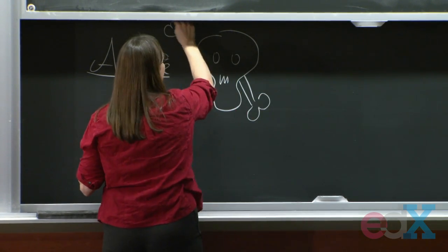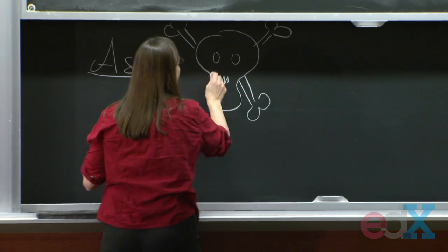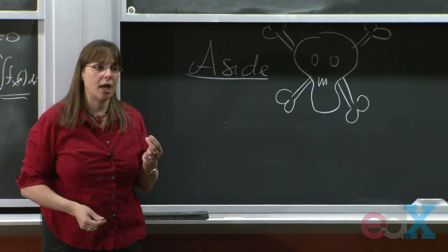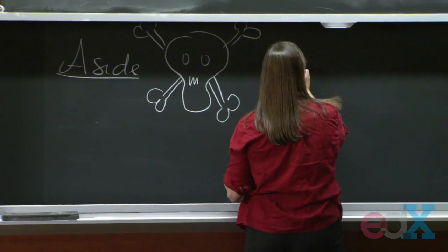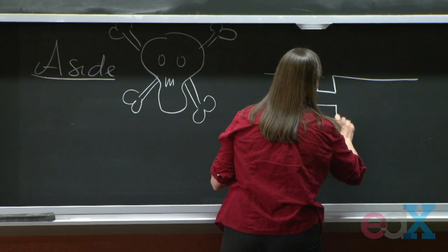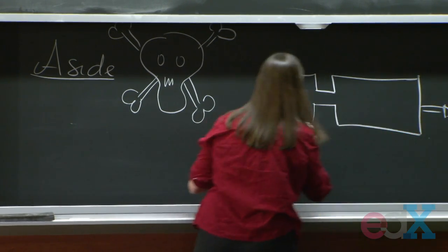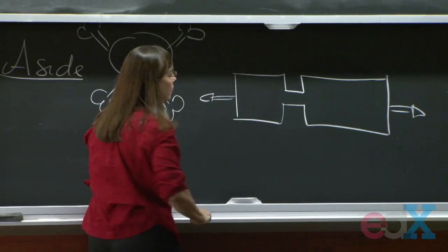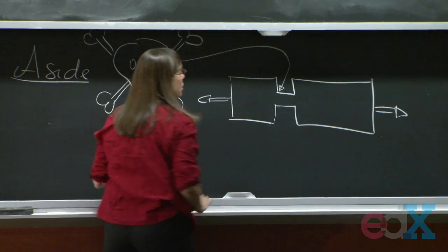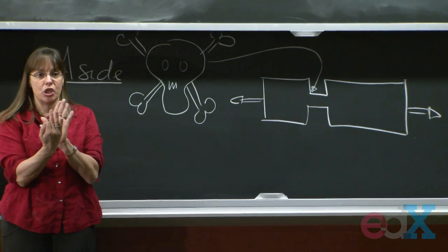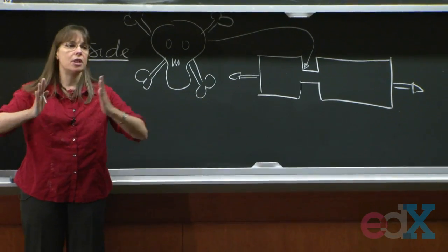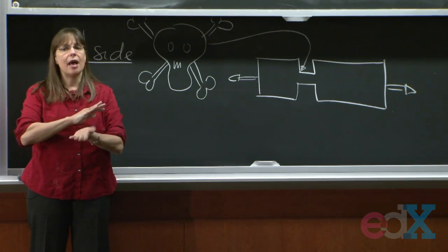So it's not like an aside that doesn't matter. It's an aside that actually matters. Okay? It's very important when you design things to realize that if you make a structure that has sharp corners, like that, and you load it like that, the depth is in the change of sections. See those sharp changes in sections? At those points, our nice assumption that everybody moves the same, the strain is the same everywhere, breaks apart.